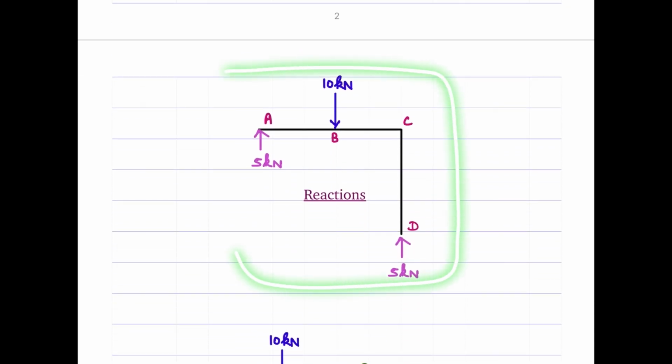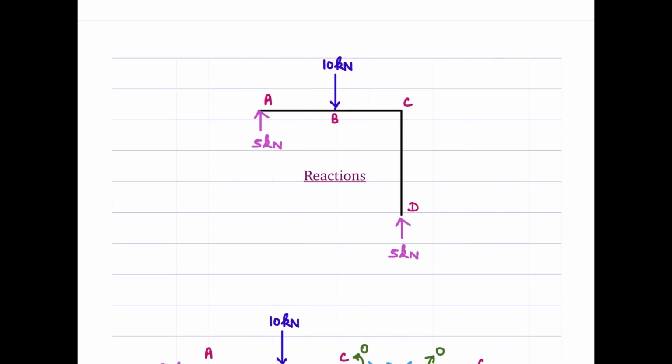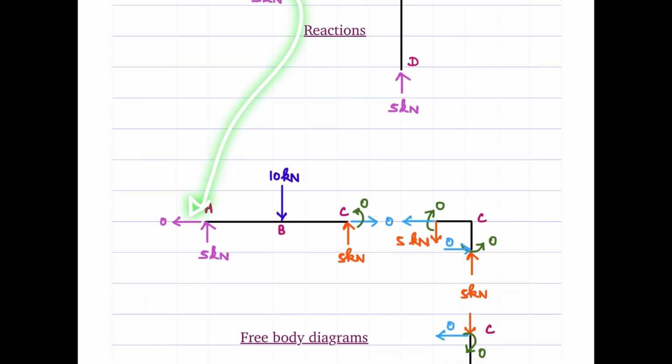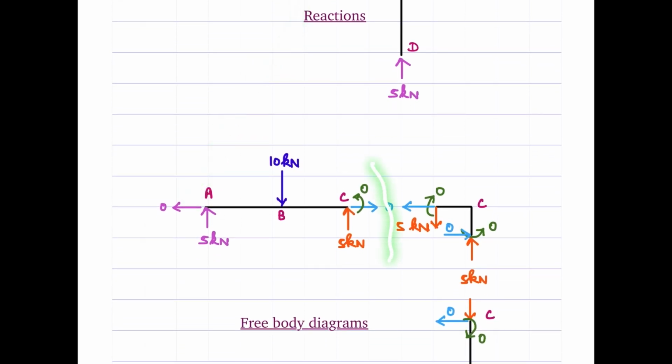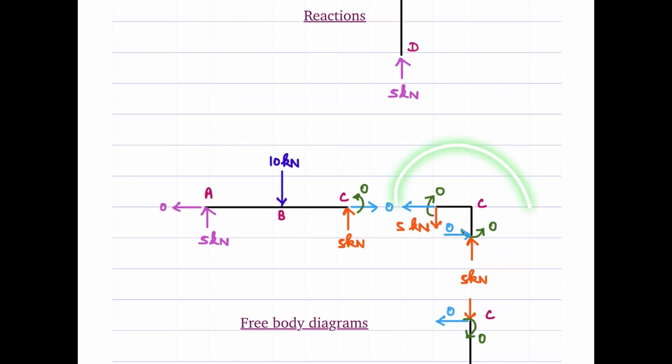We are going to do what next? We are going to draw the free body diagram for each member here. Now to do that, first we need to take this member. We are going to make a surgical cut of the member AC somewhere here, and we are going to show it here. We need to also consider this reaction here, right? So this reaction is shown here, and we made the cut here. Similarly, we are making a cut very close to the joint here, and we are also detaching the joint. The joint is shown here separately.